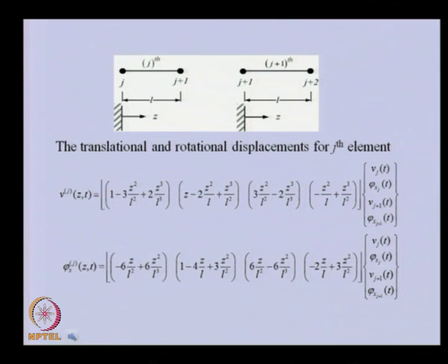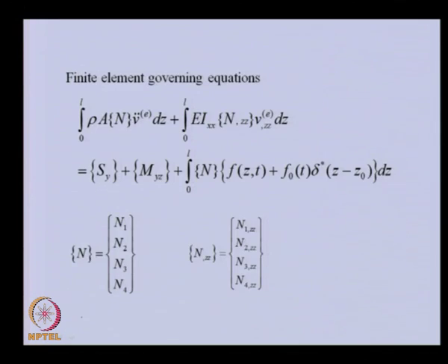And if we want to check for higher order, we will see that these shape functions may not be compatible for second derivatives. If we take the derivative once more and predict the value at the common node from these two different elements, we will see that they will not match. So now we have chosen the shape function of third degree, and we have obtained the explicit form of the shape function.